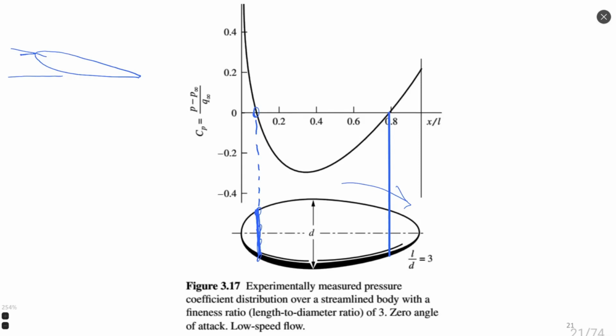I also think that there is a methodology when angle of attack is known and we can apply formula to recalculate pressure coefficient in this case. Do not forget that control of airplane in such case is caused by a flap. Okay, it can rotate just the final part of this wing. So we are changing angle of attack of just flap part of the wing, not the complete wing. So, but I think it is also possible to provide correction.